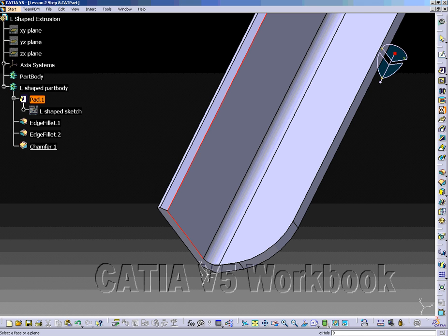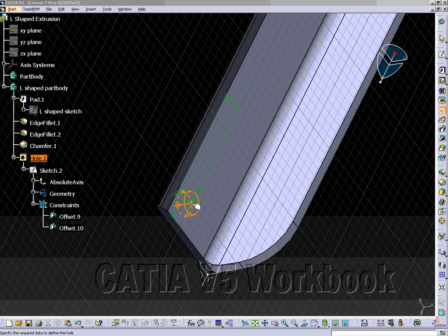Select the Hole tool from the Sketch Face feature toolbar located on the right side of your screen. The lines and surface must be highlighted. The hole definition will now appear on your screen. A highlighted outline of the hole will appear on the part with the constraints that show the distance from the two edges selected previously.